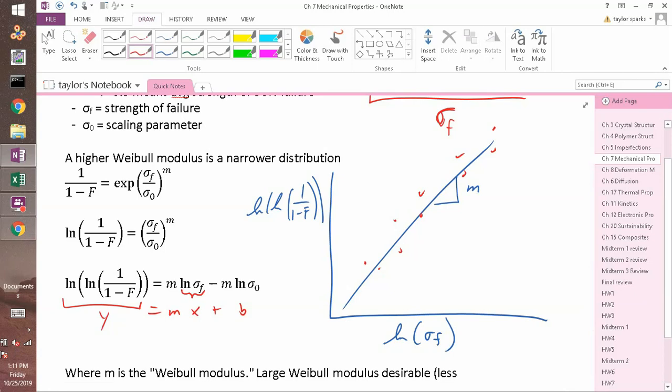It's a great question. Now, ideally, when you fit this, all of your data would lie right on this line. That would mean that the data that you measured is a mathematical perfect fit to this mathematical equation which we came up with of Weibull statistics. That may not be the case, right? It might have some scatter. You could actually put an r-squared value to this and see how well it fits. And if it doesn't fit, then you probably shouldn't trust this because it'll have low confidence in the numbers it spits out. But if it fits okay, let's say the r-squared's better than 0.9 or so, you start having more and more confidence in this as an approach, okay? Everybody with me?